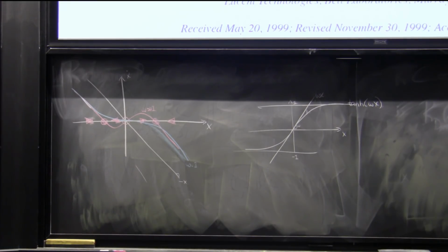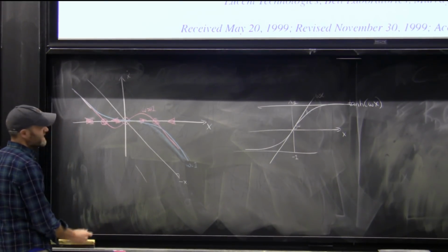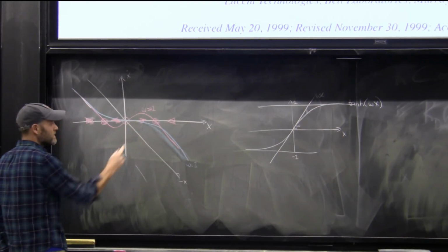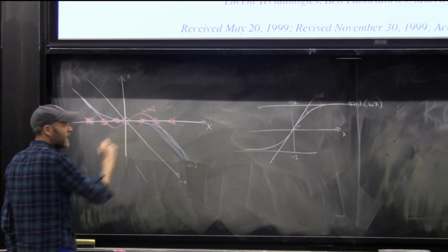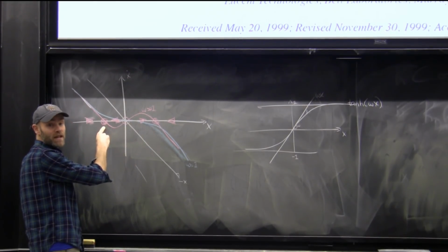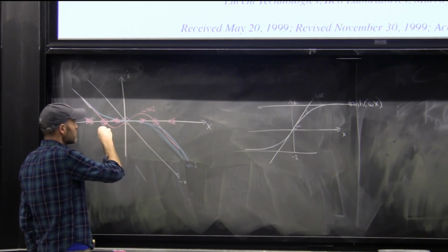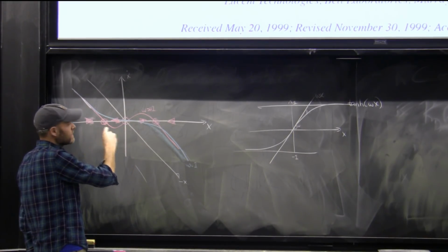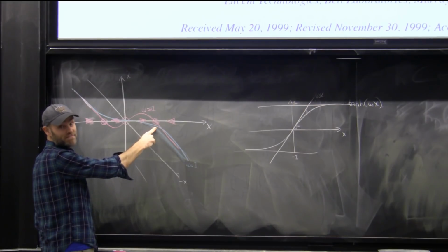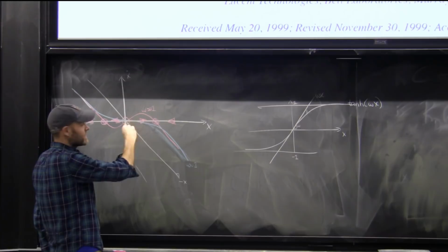So why is that possibly memory? Well, I have to do a little bit more, but first of all, it's interesting to think that for a lot of different initial conditions, I lock in to only a few possible states, 2 possible states. This one's close to 1. This one's close to -1. You could think of this kind of like a latch, a memory element. It snaps in.